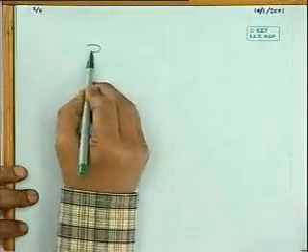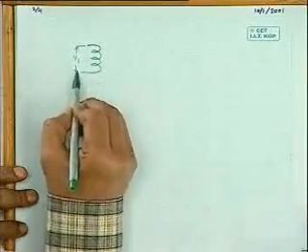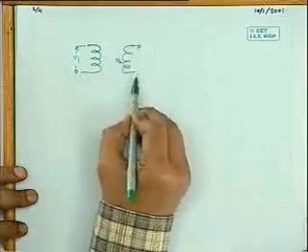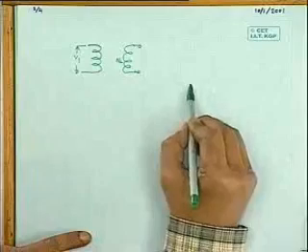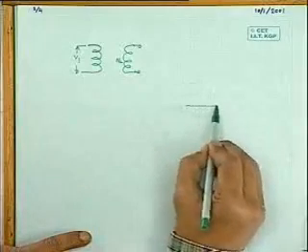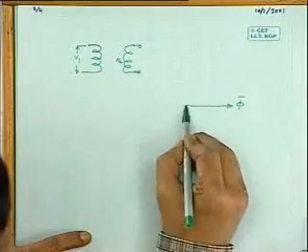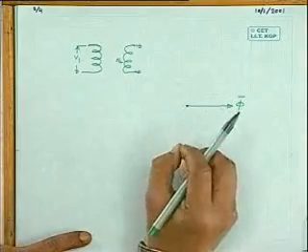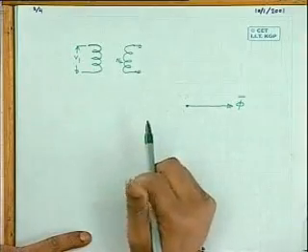Now, with this in mind, in an ideal transformer, once again I draw this one. This V1 is the applied voltage, and the secondary is open circuited. I have not connected anything here. How will the phasor diagram look? Flux will be produced. So suppose this is the flux phi phasor. Of course, the current required to establish this flux is as small as possible, like this, a small amount of current, or in that extreme situation, no current.